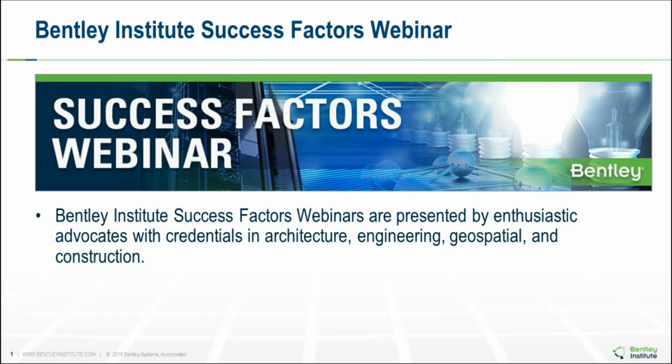Another question. So the user decides what you are trying to optimize, correct? You can optimize on cost, minimum stress, location, number of supports. Correct. You pick and choose what criteria you want to optimize for. You check that on, and sometimes you have to assign an allowable for support forces or a different ratio, but you can pick that.